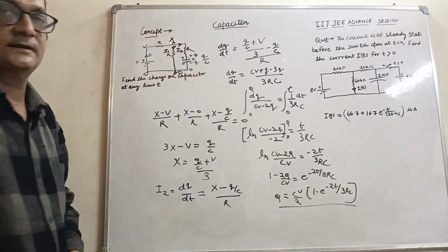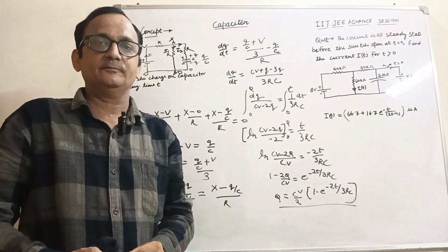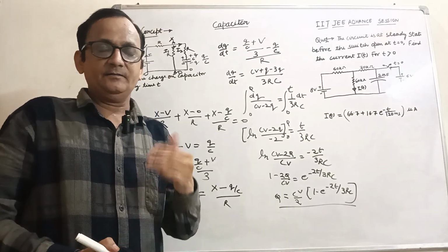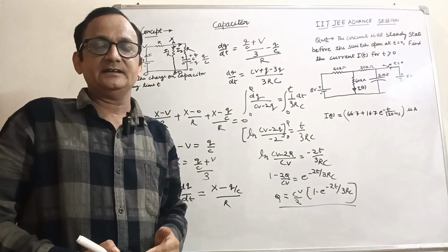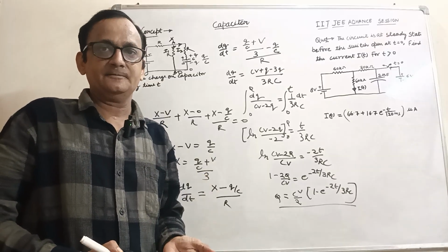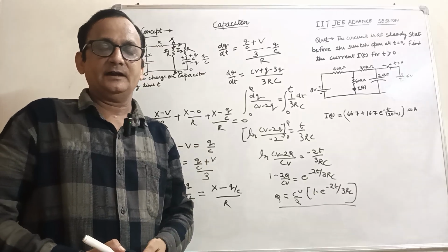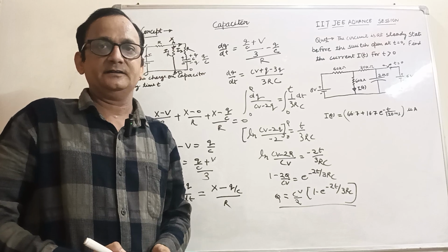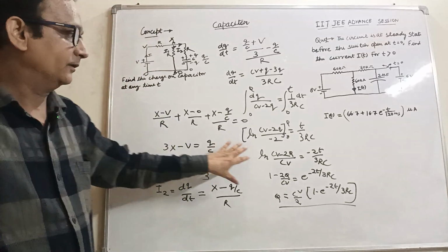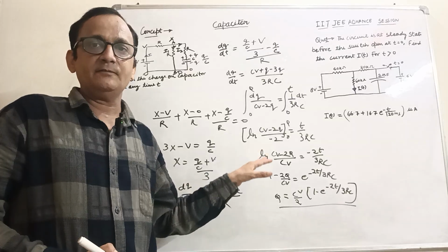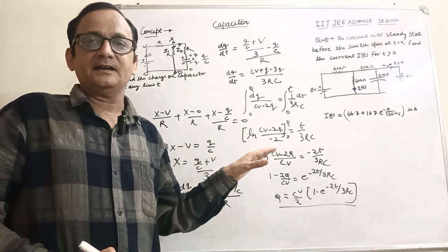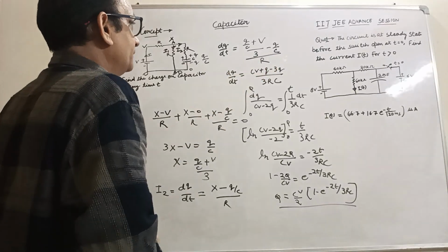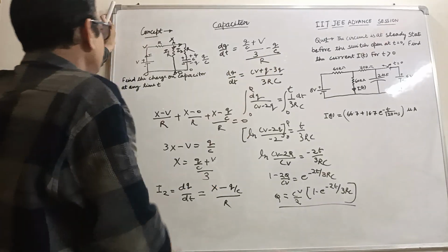So a capacitor never charges 100% in finite time. After 5 times the time constant, that is 5RC, the capacitor would be 99.3% charged. For the condition where the time is one time constant RC, the capacitor only charges 63%. So we approach the next problem.